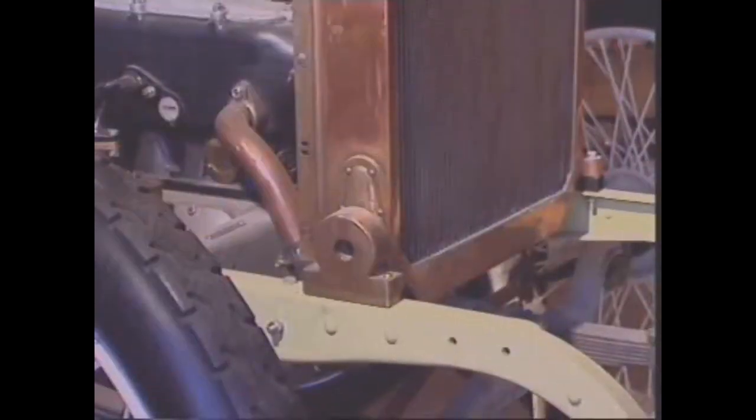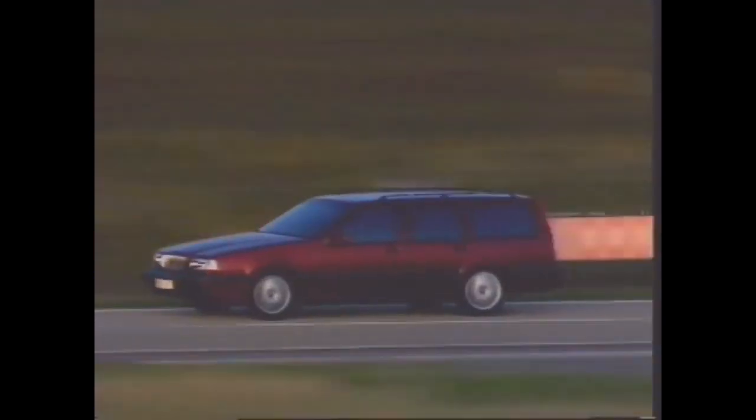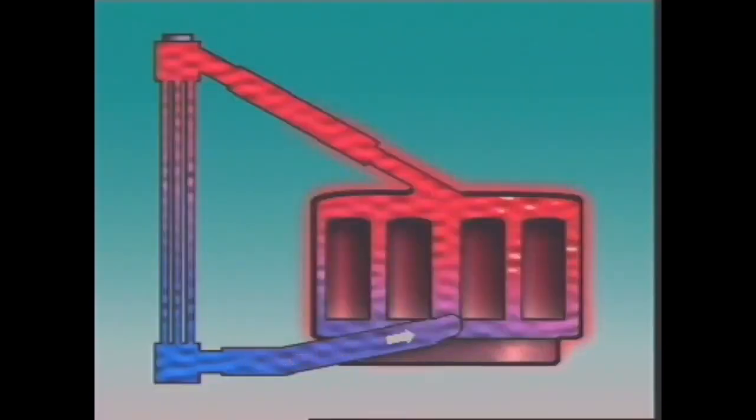It was common in older cars which had low-powered engines and high, narrow radiators. In modern cars, the engines are more powerful and radiators are low and wide, and a thermosiphon process couldn't move the coolant quickly enough. Instead, a water pump forces it through passages called water jackets in the engine block. It collects heat and becomes hot itself. Heated coolant then returns to the radiator for cooling. And the cycle is repeated. Heat is removed from the engine and dispersed.